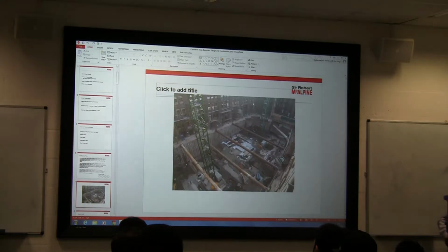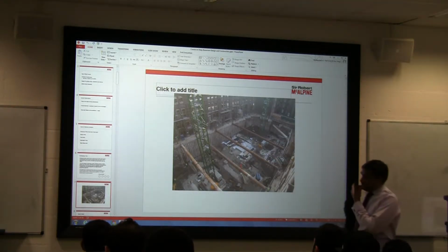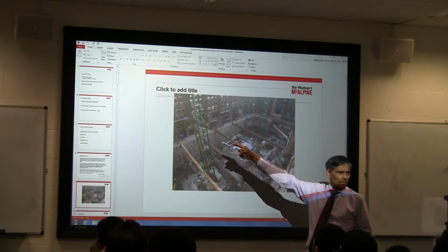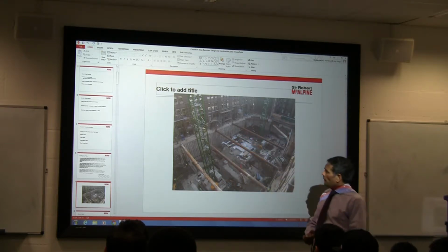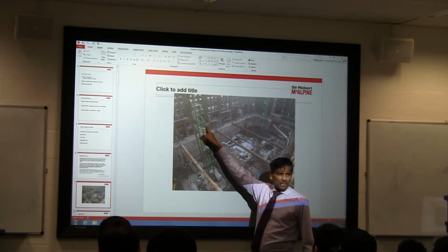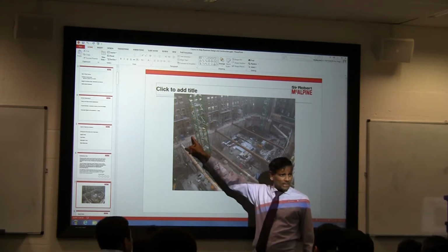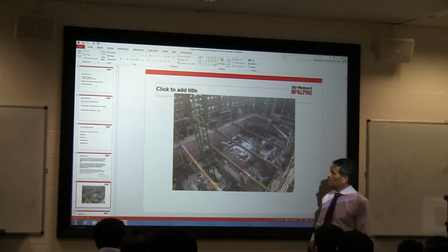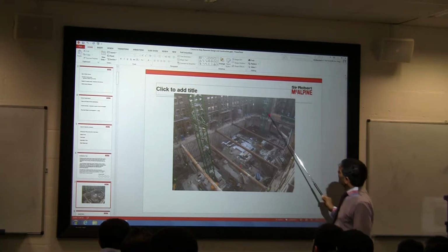The next one. This is one of the contiguous piles we have done in London, as you can see, surrounded by all sorts of buildings. Next door, very close to the building, as you quite rightly said, there's a big capping beam, because that capping beam is what is carrying the building column load directly. You understand? So that's the capping beam.